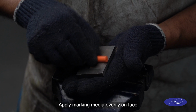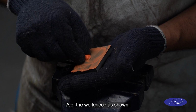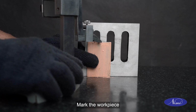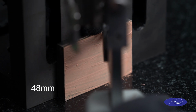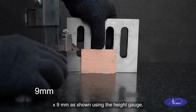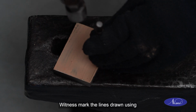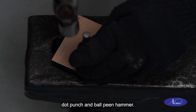Apply marking media evenly on face A of the workpiece as shown. Mark the workpiece to 75 into 48 into 9 mm as shown using the height gauge. Witness mark the lines drawn using dot punch and ball peen hammer.